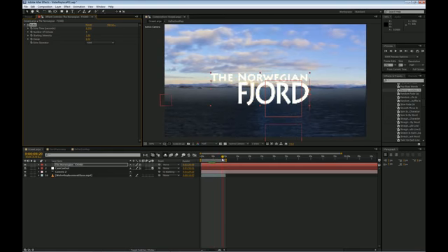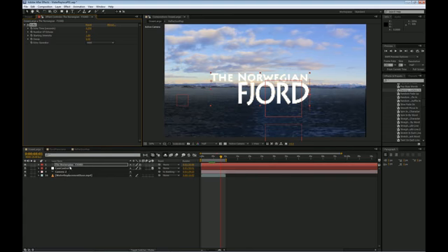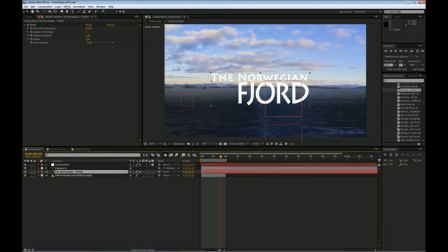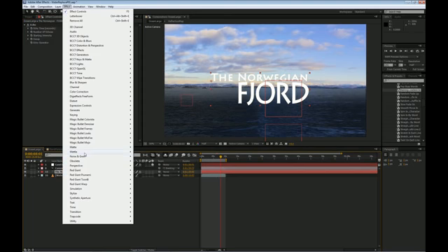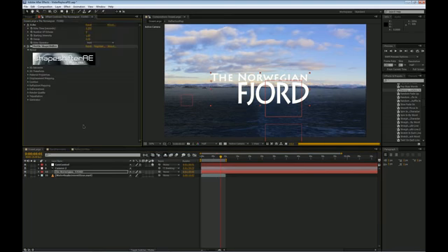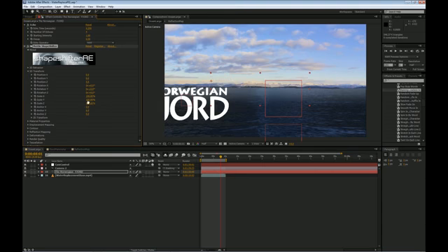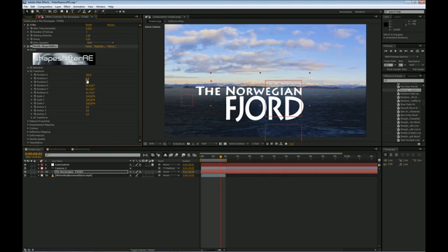I want to make sure that at 8 seconds my title is centered. So what I'm going to do is go to 8 seconds and apply Shapeshifter to my title. Now, of course, my title is a little offset. I'm going to go into Shapeshifter and change the position using the 3D transform inside Shapeshifter. I'm going to position this on the x-axis at 650 and on the y-axis at -150.